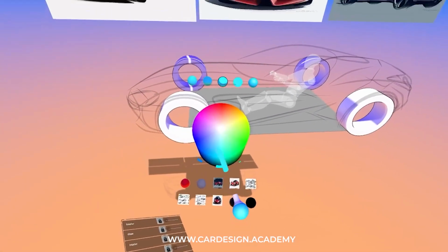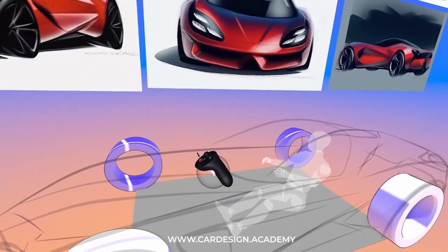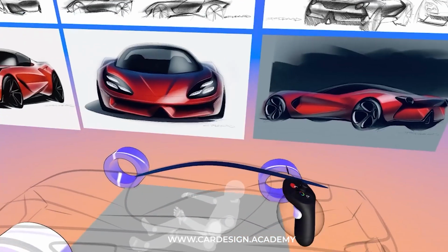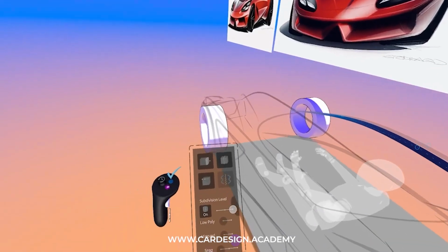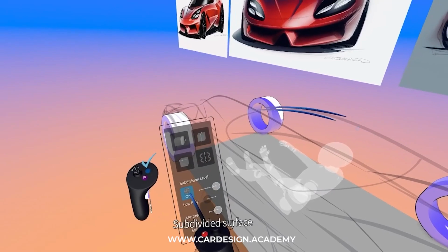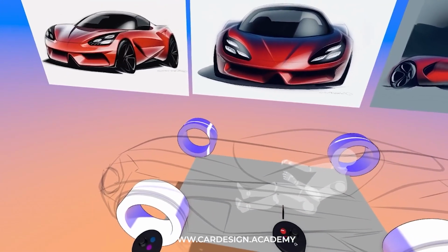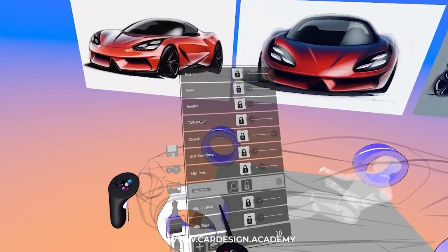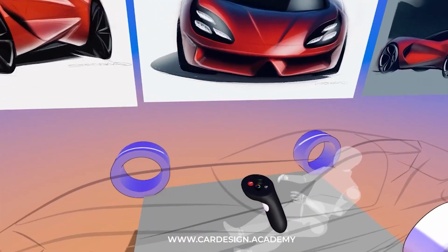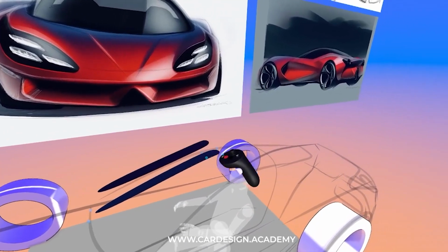Just to give you an idea of just quickly building, let's say, the canopy. There's four points right there. I can also make it symmetrical by turning on a mirror plane. So I can work real time with a mirror plane. I'm just going to create a quick centerline ribbon.